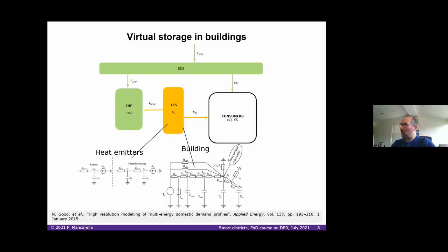And in fact, when you model it, as Carmen was showing in the notebook before, you see in the model of the building, and by the way, it wasn't the full model as Carmen highlighted, those spikes that you saw in heat production. The model we used was a reduced model, basically only one time constant and no emitter. The moment you start having all the proper time constants and the model of the emitter, especially if you use a hydronic system, you don't see those spikes. That's exactly because this all adds buffers, all adds virtual storages.